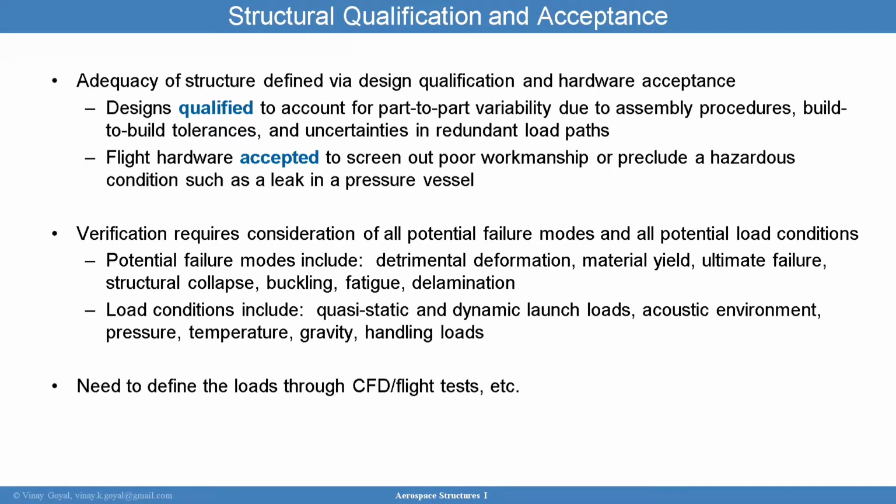It's going to be a flight design of the same drawings as what you're going to potentially fly. And so that particular structural flight design, which has the same manufacturing, has been built with the same processes as the production flight units, that particular design is qualified through a test program.